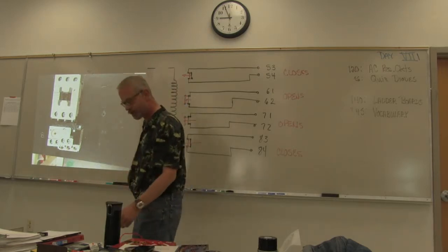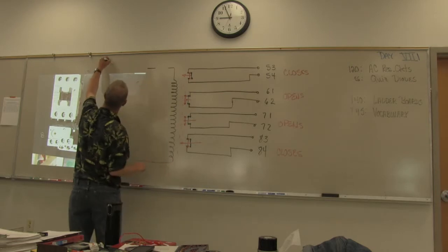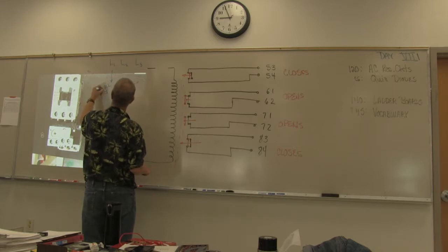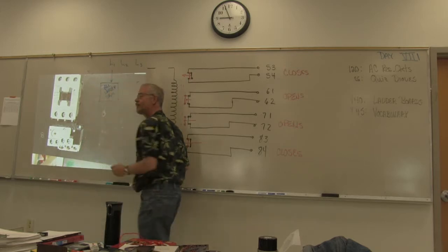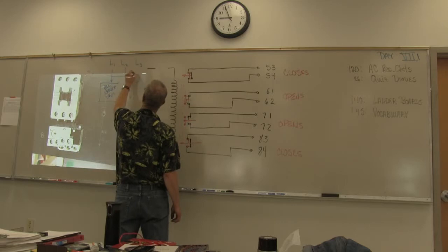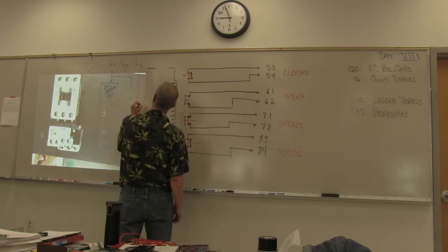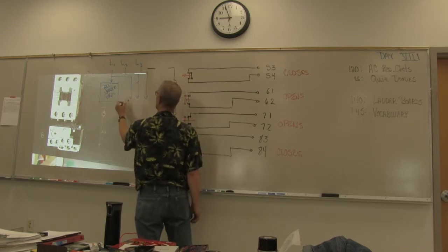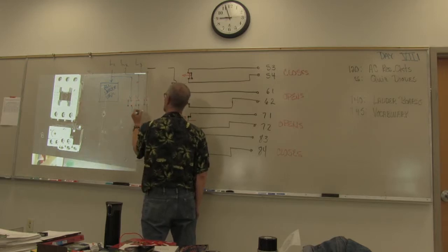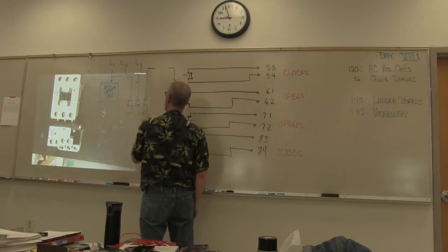A lot of times on your motor controller what you'll see is this. You'll see that you have 3 phases, L1, L2, and L3. And L1 does all of your ladder logic. Generally, all your ladder logic is done with 1 phase. And then what we'll do is we'll take L1, L2, and L3, and we will put them into a normally open setup, 3 of them together, all controlled by the same coil. L1, L2, L3. There's our contactors,